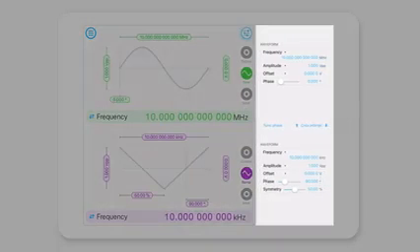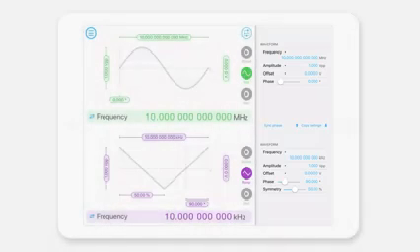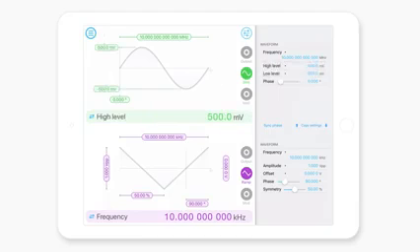This is where you can set the frequency, amplitude, offset, phase of your waveforms, but you can also quickly select between alternate units. So we might want to characterize the high level and low level voltages of the signal. We might want to specify the waveform period instead of frequency, and we might want to be able to quickly adjust the phase using this little slider here.